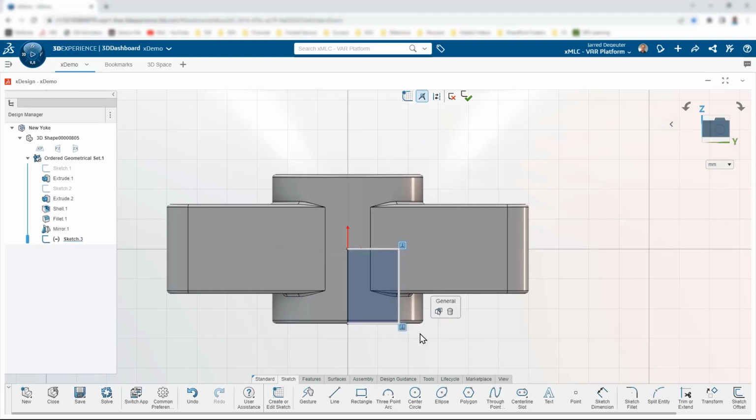So check this out. I'll go ahead and make my little cutout here, and let's get a little axis to revolve this around, right? Because we're going to be making a revolve. I'll change this to some construction geometry just for dimensioning purposes. By the way, you might be happy to know that the diameter style dimensioning technique that you have from SolidWorks is carried over here as well. So we can drop in that easy to use diameter dimension, pop in our angle, and we should be ready to do our revolve.